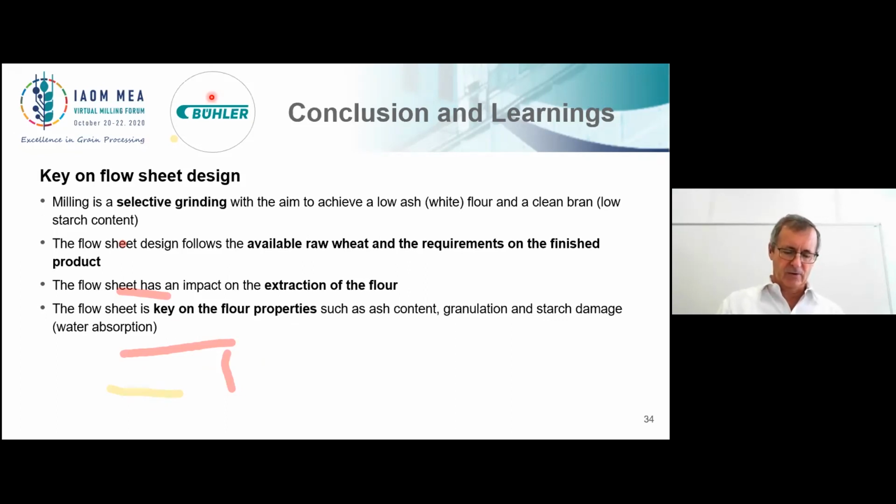So let's say wheat intake and wheat storage is very, very specific. Every miller has his own size and number and turnover. I can only talk about cleaning and milling because this is more standardized. So now I give a number. Maybe I'm not that specific, but we can say 0.8 to 1 kilowatt hour on cleaning.